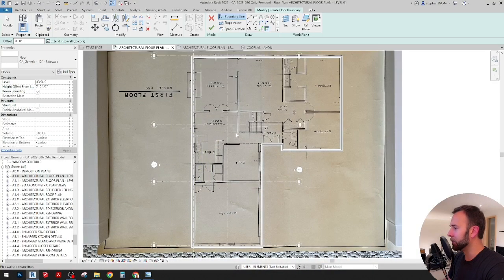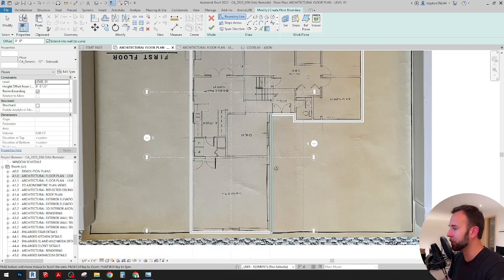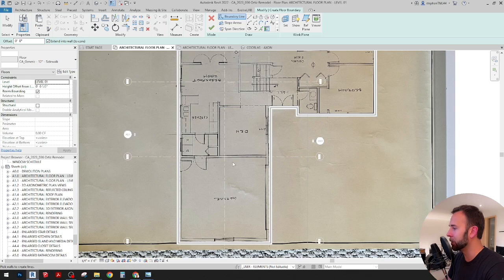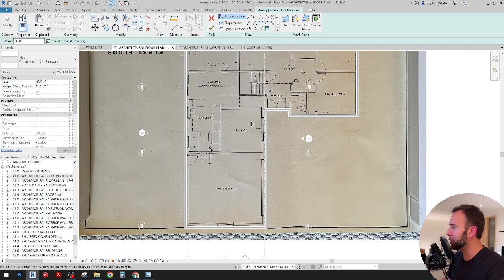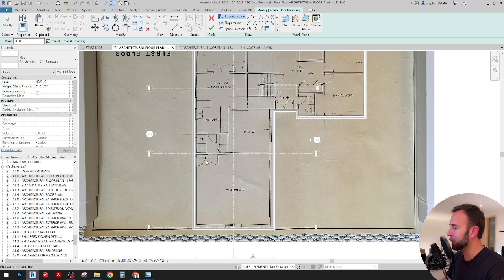Definitely not sufficient for our floor framing, but we want them to be for the new area, so we're going to be replacing those at least up to grid line 2, which is the garage area. Everything beyond that, we'll have to do some discovering as we do selective demolition, but I'm going to model them in as 2x12 joists in this area.